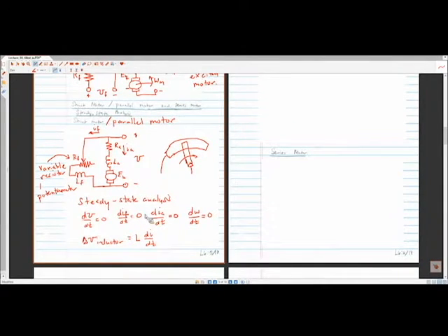And so in the steady state analysis, we're going to ignore the contributions from the inductors. These are almost like silent electrical elements in the system. This is definitely not going to be the case when we get to dynamic analysis of motors, but for steady state, there is no voltage drop across the coils from the inductance. There's a voltage drop definitely from the resistance of the coil.